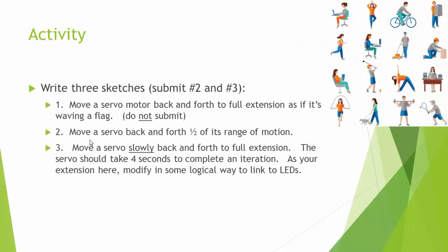Okay, so for your first activity for today, I'd like you to write a few sketches. One to move the servo motor back and forth to full extension. Don't forget your delays to allow it to reach that. Another to move the servo back and forth half of its range of motion. And finally, a command to move the servo slowly back and forth to full extension. This will take a little bit of creativity. Make it take 4 seconds to complete that iteration.